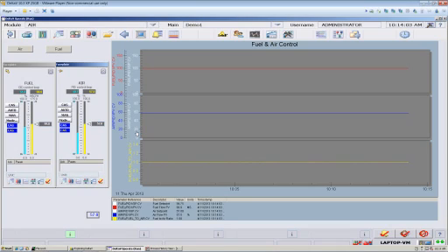I want to start today, much like we did last time, and that is I want to start with a compare and contrast and show the alternative method, the old school, high gain, fast tuning, Ziegler-Nichols method. In my trace here, the red trace in the top third indicates my fuel flow. The blue trace in the middle is airflow, to a burner. I'm burning this fuel with this much air. And the yellow trace on the bottom is indicating my fuel to air ratio. That's what's most important to me.